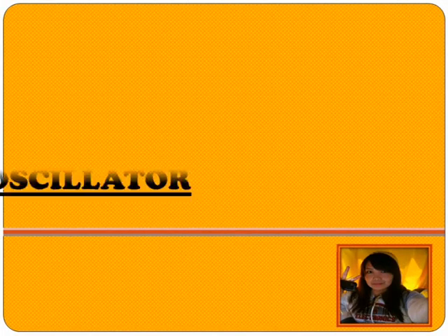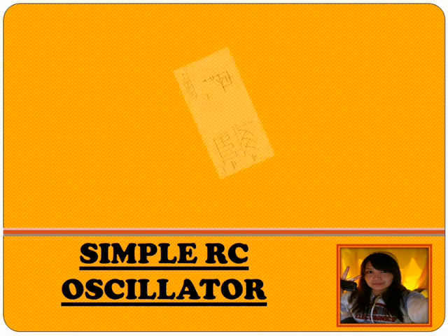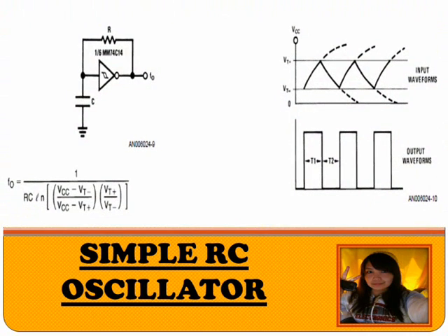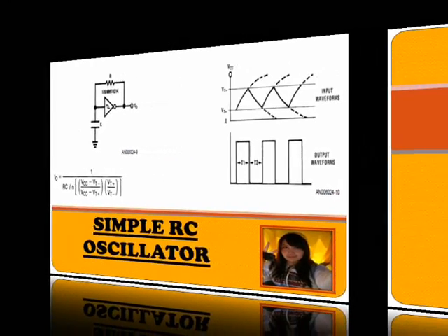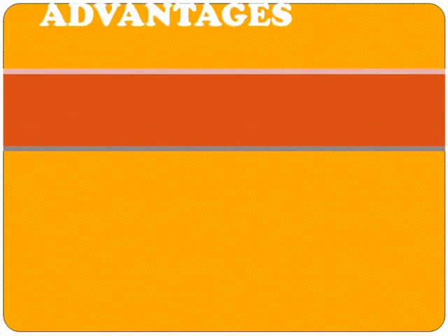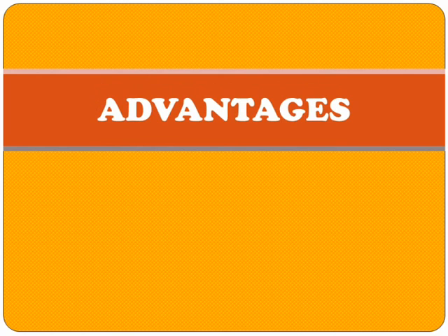A CMOS application note wouldn't be complete without a low power application. This figure shows a simple RC oscillator with only 6 resistors and capacitors, and 1 hex CMOS trigger. 6 low power oscillators can be built. The square wave output is approximately 50% duty cycle because of the balanced input and output characteristics of CMOS.